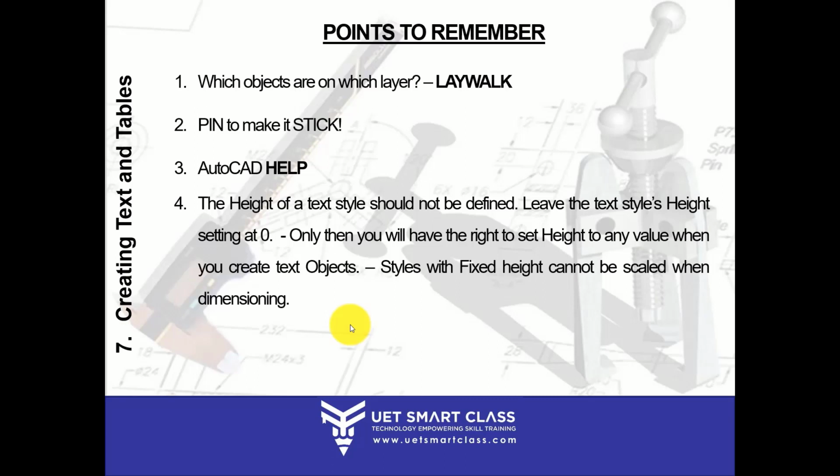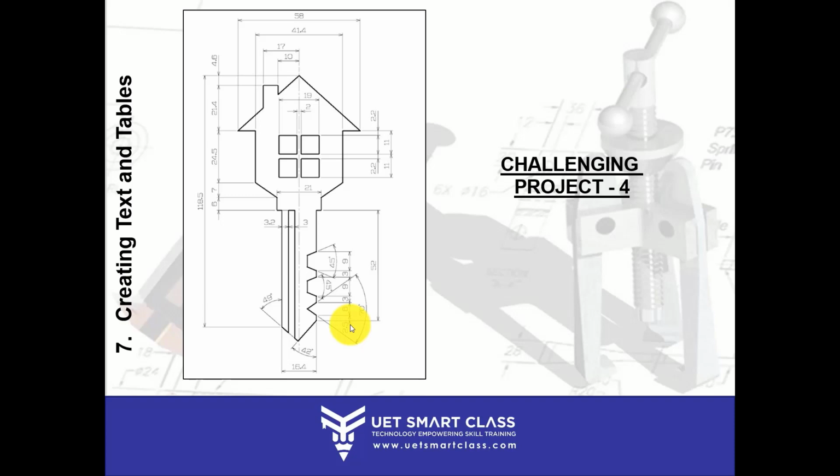And keep practicing setting annotative text so that whenever you set scales, through annotation scales, AutoCAD automatically changes your text height as per the scale given to your paper. Okay, so there will be no problem when you're plotting or printing your artwork. Okay, so that's all for today.